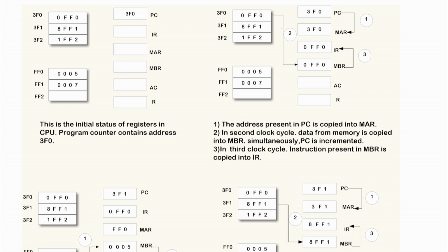Assuming it had been a 2-word instruction, a double address instruction, you might have taken a longer size, maybe 0FFF, and the other part of the address would have been there. In that case you would first bring this to IR, maybe the IR would also have been elongated, then this part of the instruction would be taken from the memory buffer register to the IR. After 2 memory read operations you would be able to understand the meaning of the instruction.